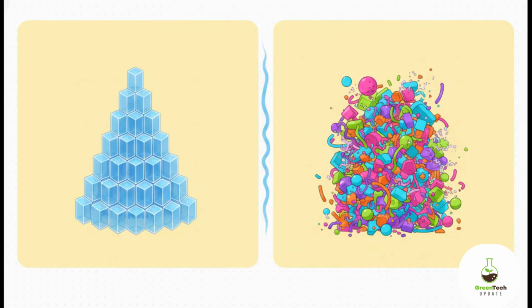Let's compare cellulose and hemicellulose for a second. Cellulose is this rigid, crystalline array of D-glucose units. That highly organized crystal structure gives it some serious thermal stability. Hemicellulose, well, it's entirely amorphous. It's a messy, irregular mix of different sugars like xylose, glucose, and mannose. Because it doesn't have that tight crystal structure, hemicellulose breaks down way earlier in your reactor.